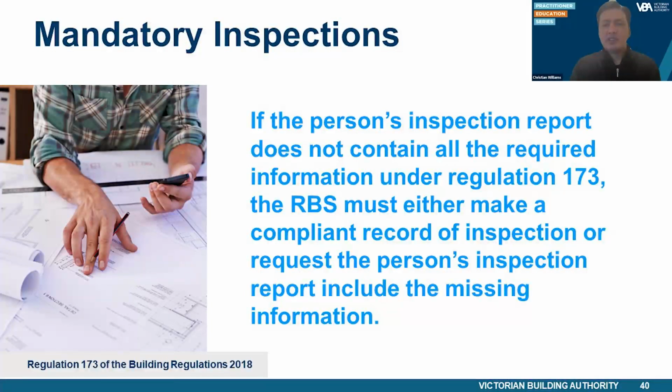Persons who carry out inspections of building work on behalf of an RBS must either be an appropriately registered building surveyor, building inspector, or a prescribed person pursuant to Regulation 174. The inspector can only be engaged by the RBS and must act on behalf of the RBS under their direction.